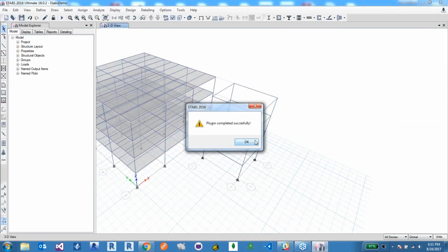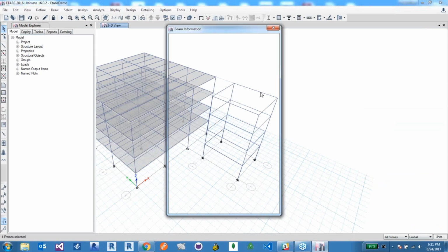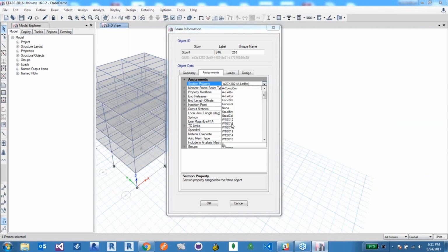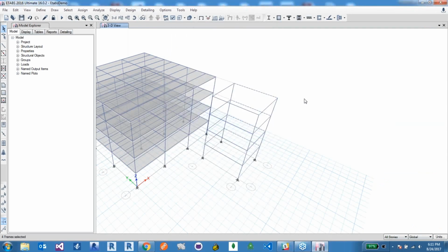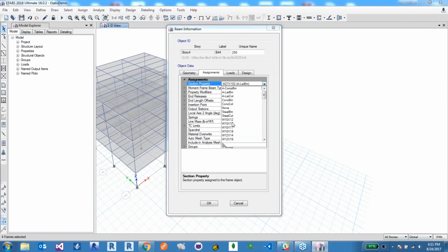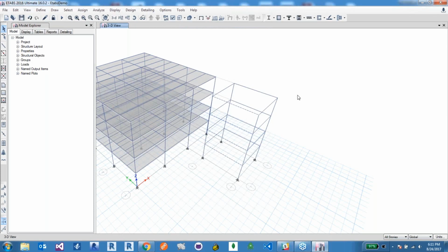Let's go back to Etabs. Now in Etabs, for example, I can change some of my sections that I have here of those elements. I'm going to change some section properties to W10 by 15, for example. And I'm going to do that also for the other beams on the other side, say 10 by 15, and I'm going to upload those changes to the server.